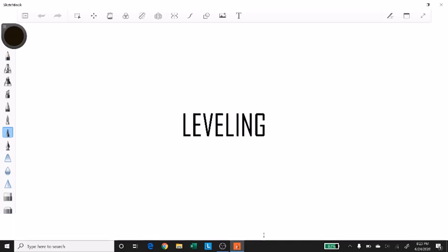So in leveling, basically what we do is we either try to create vertical control over an area, or we might try to execute a project by carrying out a layout survey. It could go either way, but what I mean by gaining vertical control or laying out points is that in the vertical plane you need to find out the relative height of points. That means I need to find out the vertical distance, or elevation difference, between different points. So that is called leveling.